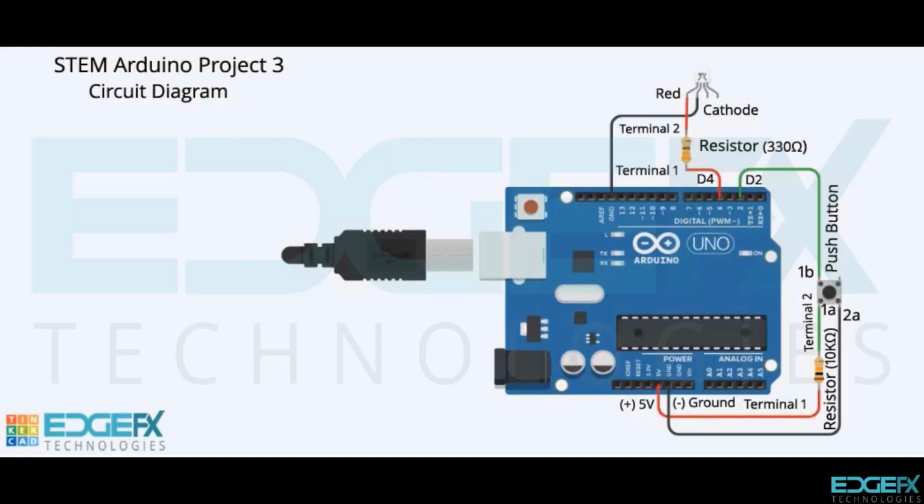To generate red flashing light. To summarize this step 3, we connect push-button switch, RGB LED, and Arduino, such that when the Arduino is powered and we press the push-button switch, the RGB LED goes on and off, or flashes in red color for a specified duration of time, and switches off when the switch is pressed again. This action repeats itself whenever the switch is pressed.